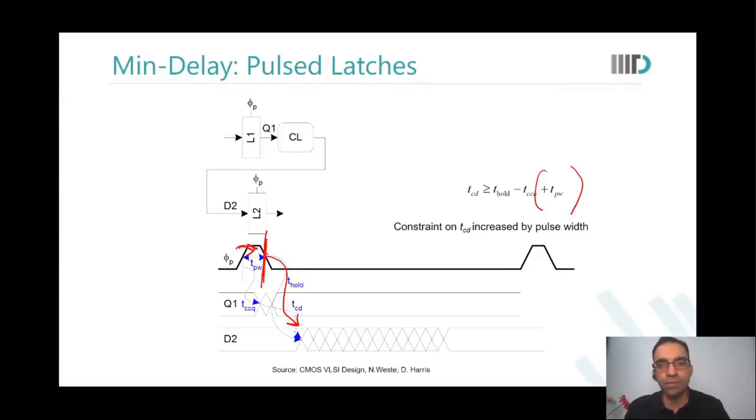We also talked about this in the previous class. So this hold always would be higher. How would we justify using a pulse latch before a flip flop? You have to look at other things also. What is the sequencing overhead of a pulse latch? As we come to time borrowing, we will see what is the benefit or the loss there. There are so many aspects.